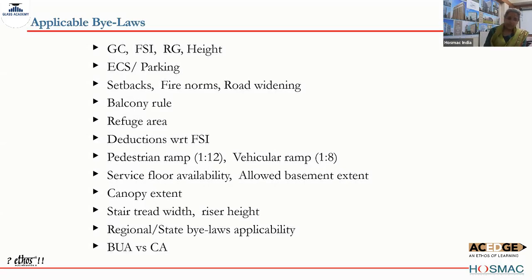So service floor is something which many architects, as well as architects sitting in the government and the municipality, do not reckon with, do not recognize. It is understood that the service floor will have a clear height of 2.4 meters from slab to slab, inclusive of the beams.